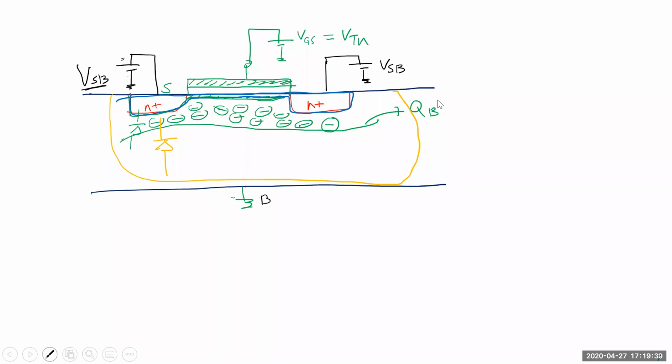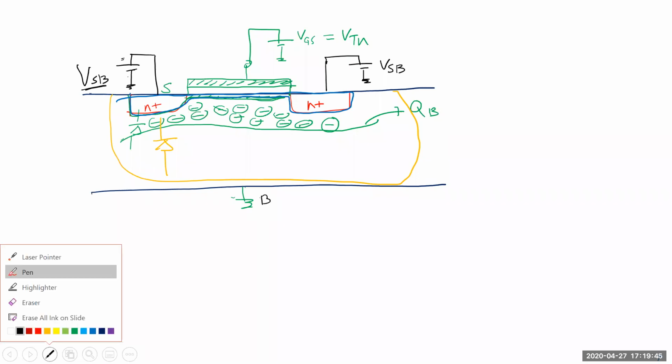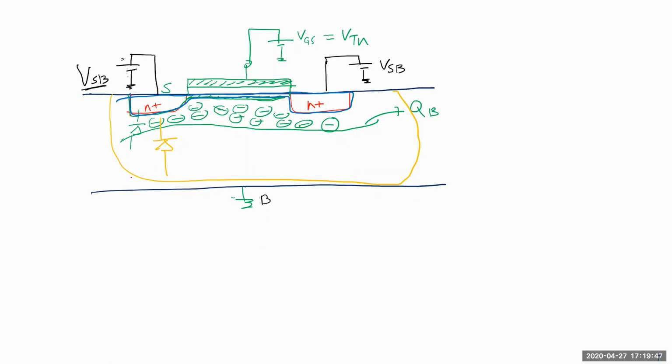Okay, so what will happen is once I apply that voltage, my depletion area, I'm just going to exaggerate it. My depletion width will increase with the depletion charge as well, right? Because I have increased the reverse bias voltage, because this is nothing but reverse biasing.